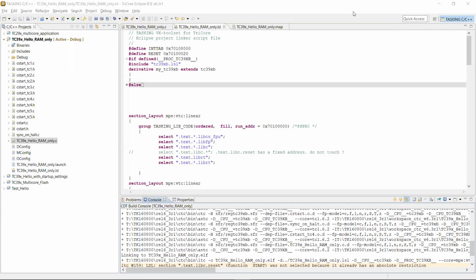So that they are small, they have to run extremely fast because they're running in a high frequency, and you want to reduce the execution time of the interrupt service routine. Then you can locate this interrupt service routine in RAM, and it'll run faster than from flash, because physically flash access is slower than RAM access.